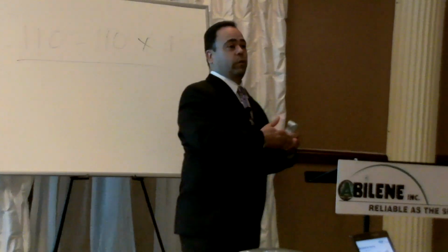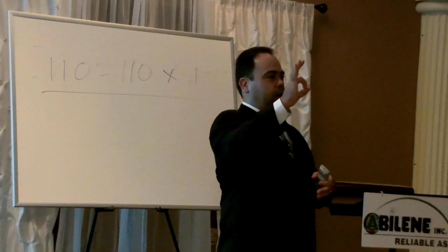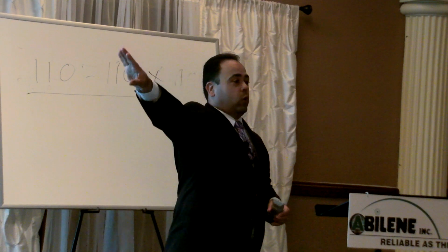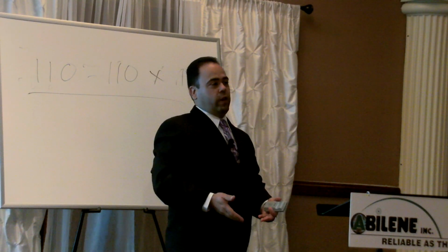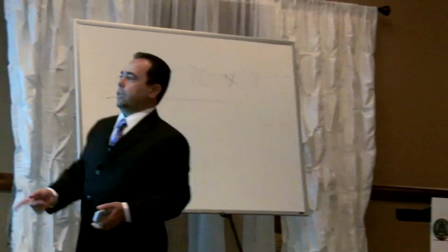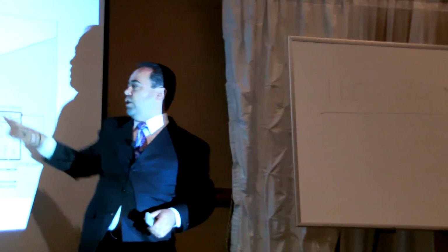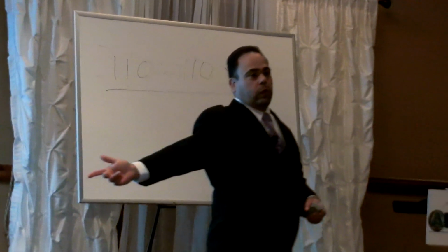So with 10,000 volts, I can get a lot more with a smaller wire, right? I can get a lot more amperage down the other end and produce and provide more electric. So as you increase your voltage, you're decreasing your amperage. Okay? That's on the primary side of the transformer. Secondary side of the transformer would always be down to house current, which is 110, 240 volts.